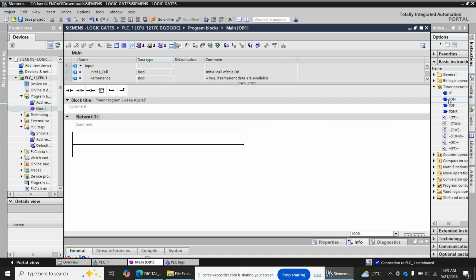So in basic operations, when the input turns on, the timer starts counting, okay. When the preset time is reached, kama ulikuwa umeset 5 seconds, ikifikiwa, then the output turns on. So tutasema if the input turns off early, kwa mfano labda una switch turn on, afu na count 1, 2, 3, alafu uka switch off before haijafikia ile preset time, then the timer resets, ina begin from 0 na output doesn't come on, right? So let's say it's an operation.